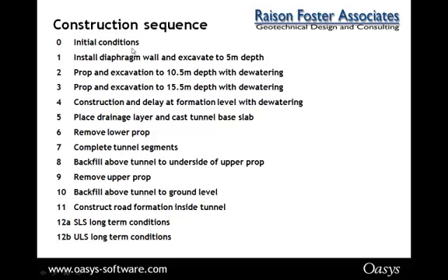So in terms of the construction sequence, this is the construction sequence. As you can see, we've got our initial conditions. We install the wall. We excavate and put the props in. There's a construction delay at the formation level with dewatering. So this picks up on one of SAFE's features, and that you can pick up a timed analysis. You've also got the completion of the tunnel segments, the backfilling, and modelling in the SLS and ULS long-term condition.